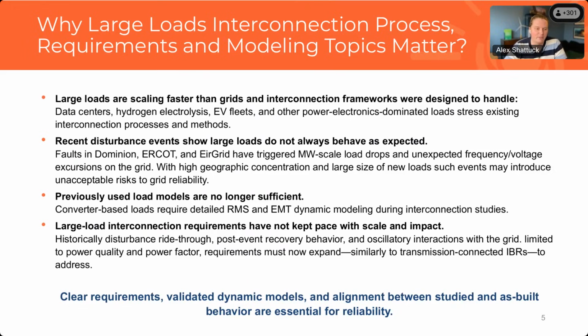So even simpler things like ride-through, post-recovery behaviors, and oscillatory interactions, there are in some areas some requirements for those, but we need to expand them similar to what we've done with IBRs, and maybe even push both IBRs and large load interconnection requirements forward in tandem here to capture this impact. So that boils down to the fact that we need clear requirements, validated dynamic models, and alignment between studied and as-built behavior. All of those things are essential for reliability.